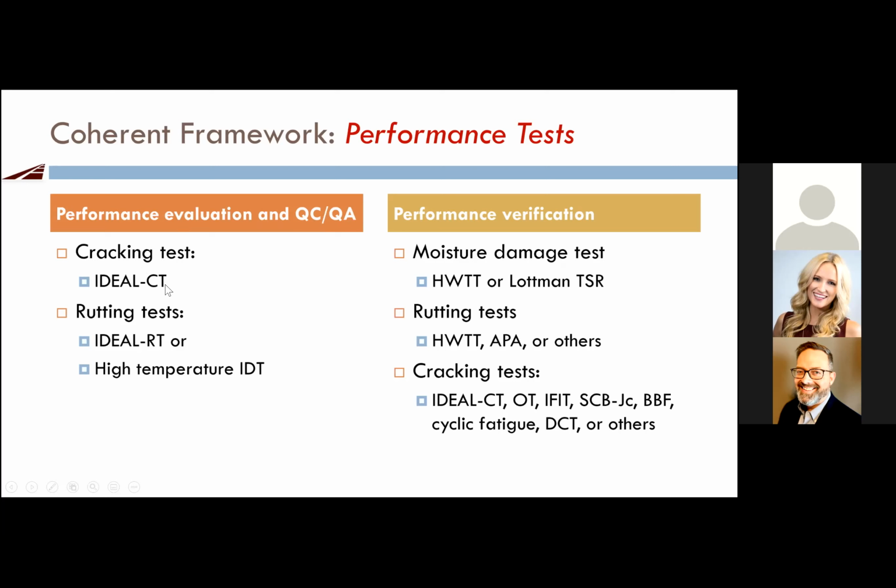For example, the ideal CT has been validated by many field test sections for fatigue cracking, reflective cracking, and top-down cracking. For the ideal RT and the high temperature IDT, all these 3 tests, you just mold the specimen, then you test it. No instrumentation, it's so simple and a very efficient, effective test. That's what the performance evaluation, the QC/QA, preferred or mandated. In order to use it as the QC test, that's the test we recommend.